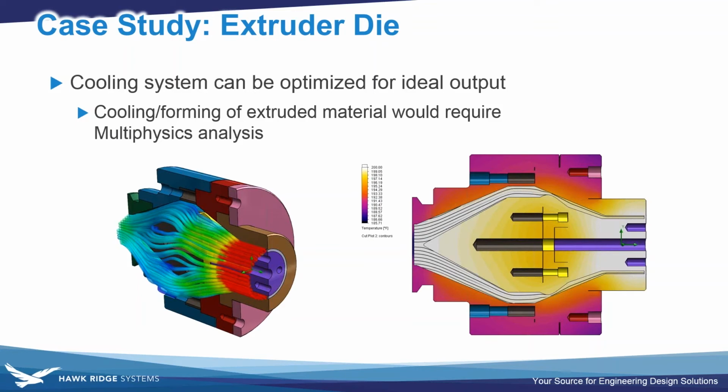While you could go a little bit further than this with SIMULIA Abaqus and potentially simulate the extruded material coming out itself, Abaqus really would not be able to give you the complex thermodynamic and fluid behavior of what the molten plastic is doing inside the die like this. So this is an area of specialty for Flow Simulation, especially compared to how easy this tool is to use. And obviously you can get all the results you would want, like streamlines, cut plots and surface plots, very intuitive for most SOLIDWORKS users to pick up.